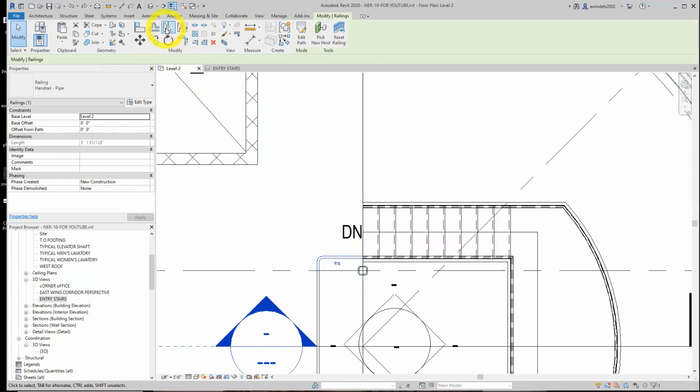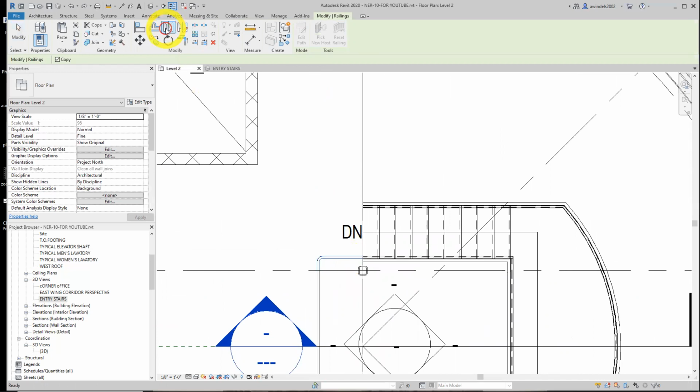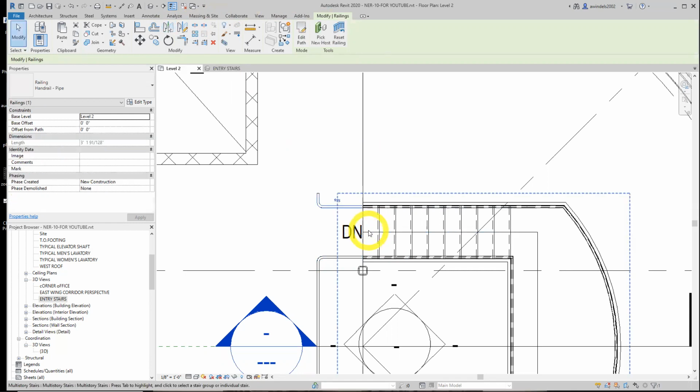Select this. Mirror, pick axis. Now, when we make the mirror, we could totally just mirror it with the 2-point mirror. Instead of picking an axis, we could. Let me pick this as my axis though. That works because it's symmetrical, evenly mirrors. You could have drawn in one 2-point mirror line, but we didn't need to because we had this line to select here. So we got that.